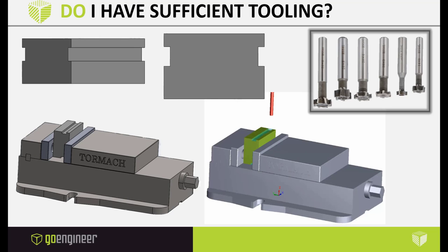Another common scenario, which can force you to be creative, is when you don't have a long enough tool to reach all of the features from 1 setup. So keep in mind any tooling limitations you may have while creating your game plan.